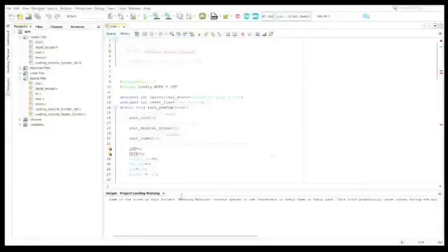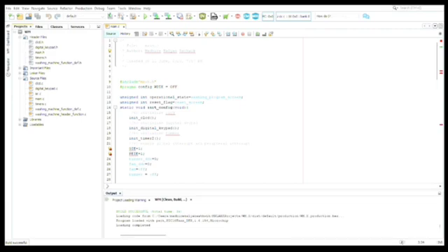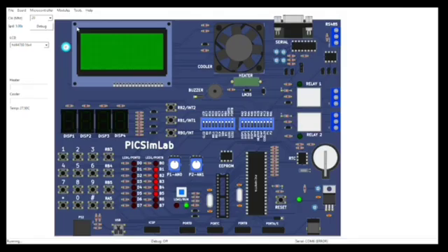Now we are going to start the project demonstration. As a starting part of the project demonstration, firstly we open MPLAB X IDE where we have programmed the whole program of the washing machine. As you can see, all the source files are here and also the header files. Now we will be using the clean and build main project option to build and generate the hex file. As you can see, the build is successful here.